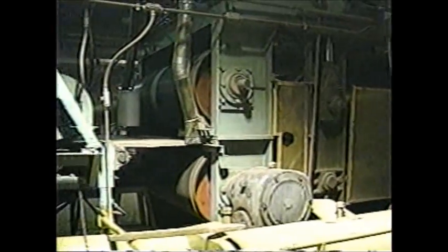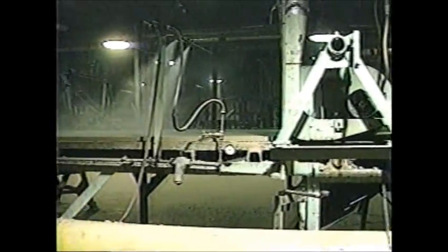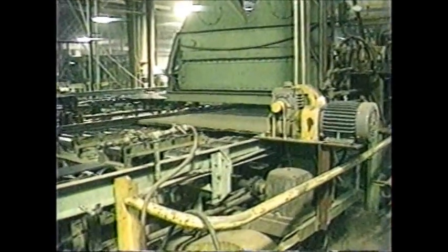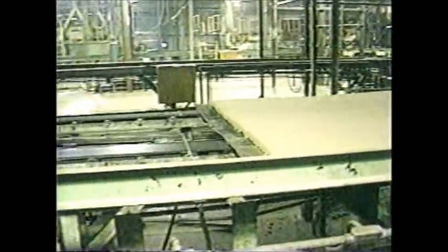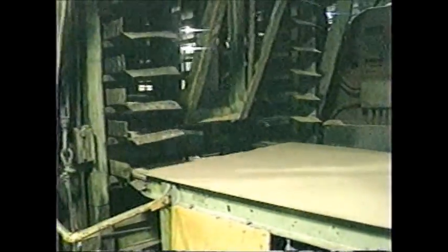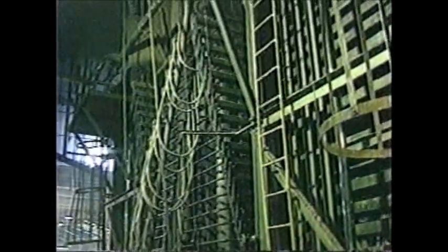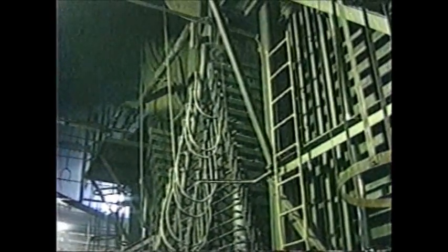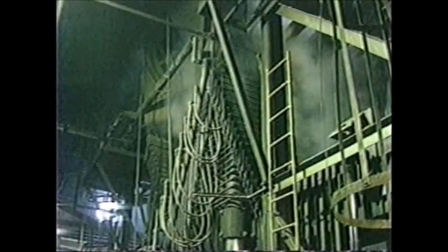After mat formation, the mat passes through pre-press rolls which compress the mat prior to the pressing operation. Mats are deposited on mild steel cauls and conveyed to an accumulating cage for loading into the press. When full, the accumulator discharges into the hot press while the newly pressed boards are discharged into a cage. The press closes and the boards are cured under heat and pressure. Upon completion of the cycle, the press opens and the process continues.